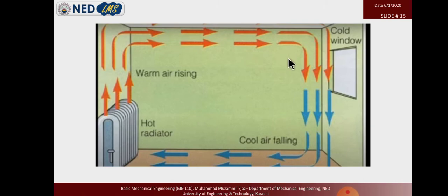But if we did it oppositely, if we placed a cold plate at the bottom of the fridge, the air in the bottom area would have a lower temperature and stay there, and the upper portion of the fridge becomes hotter, and there will be no flow.